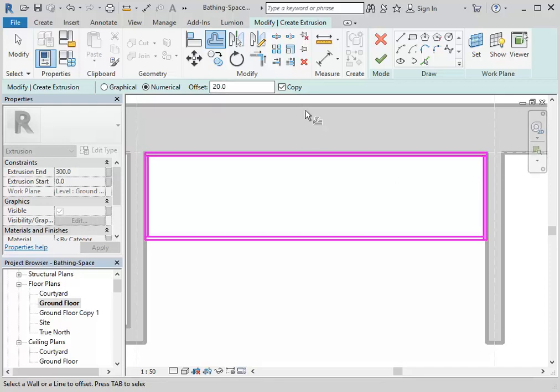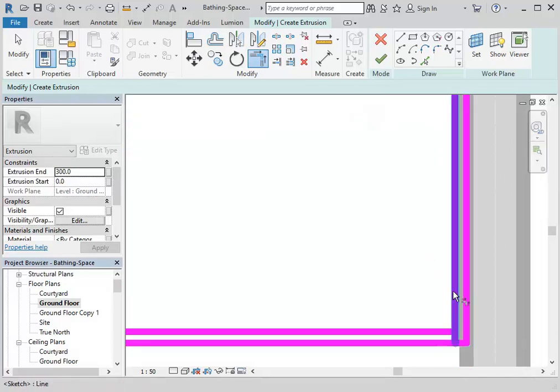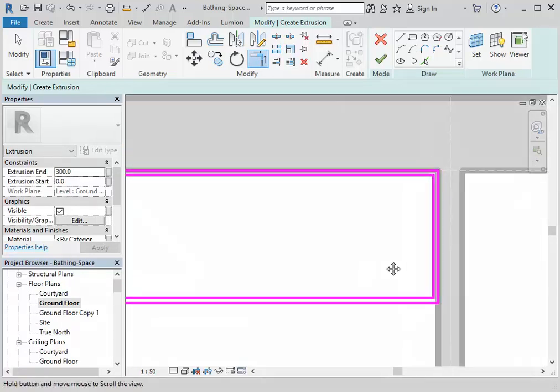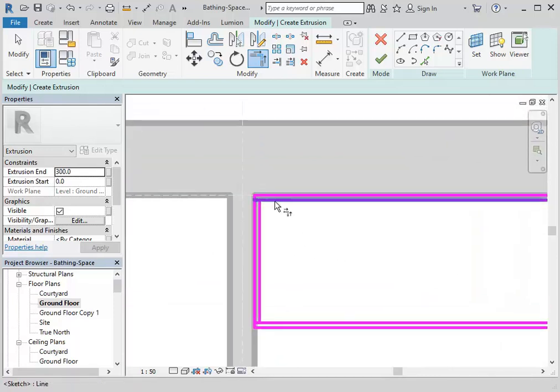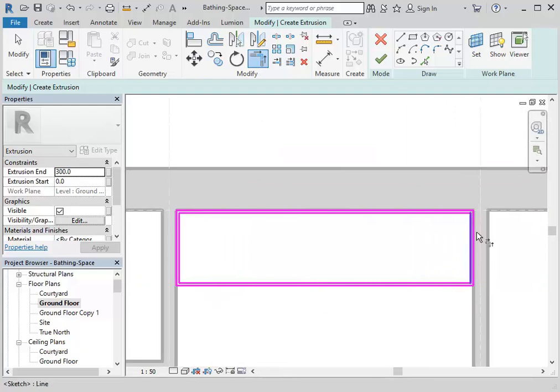So again, this needs to be trimmed because those corners need to be joined. And is anyone thinking, why didn't I do a void? If it's not clear, what I'm trying to do there is cut out the inside. And you could use a void. But I'm showing you another way here. We don't need a void because if you make a second shape inside, it cuts it automatically.